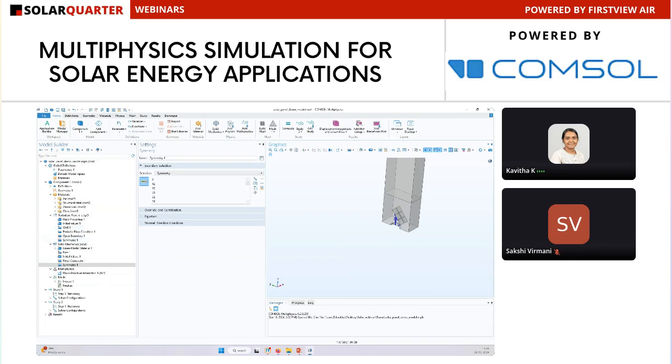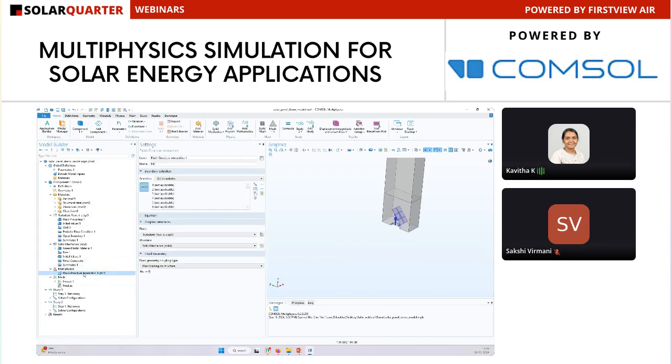So here we saw that the turbulent flow is going to solve for the turbulent flow around the solar panel using the turbulent flow k-epsilon physics interface. And the other interface is going to solve for the structural stresses and displacement due to the fluid load that is computed from the turbulent flow model. The multiphysics coupling feature, fluid structure interaction fixed geometry, will be used to couple the fluid flow boundary load from the fluid domains to the solid domains. So this corresponds to a one-way fluid structure interaction analysis.